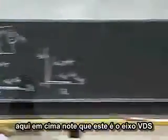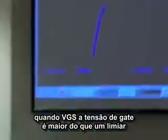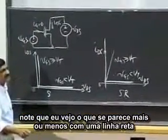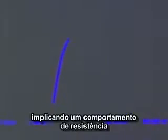Notice that this is the VDS axis. This is the IDS axis. I'm plotting IDS versus VDS. And when VGS, the gate voltage, is more than a threshold, notice that I see what looks more or less like a straight line. This is a straight line with some slope, implying resistive behavior.